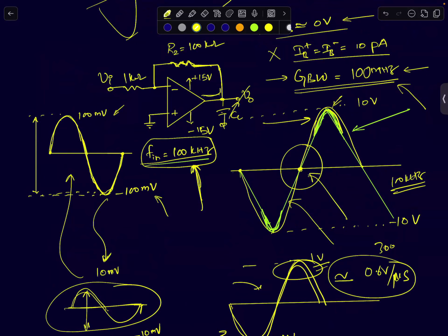Okay, and when this current is flowing, nominally when the input voltages V plus and V minus are equal, there was some nominal current flowing through the circuit. If I'm saying that the output voltage is increasing, which means some current is flowing from the op-amp, that current is a reaction. It is getting pumped out of the op-amp because a small delta V appears across the input, and it will push a current. Okay, that's how the change happens.